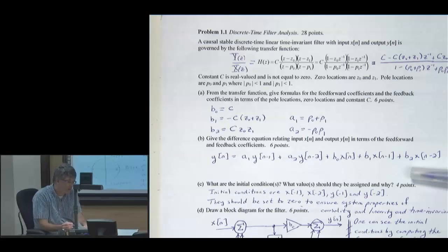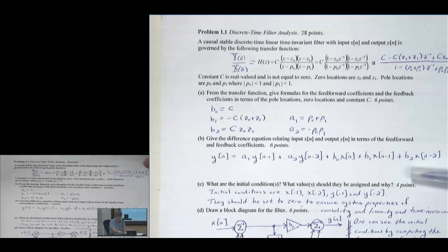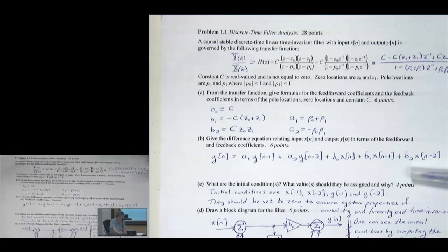Now, see, nowhere along the way have we set C to any value. You really can't set the constant C to a value that's tuned to a particular frequency until you know the selectivity of the filter. So if students did that, it just cost a couple of points. It just wasn't needed here.